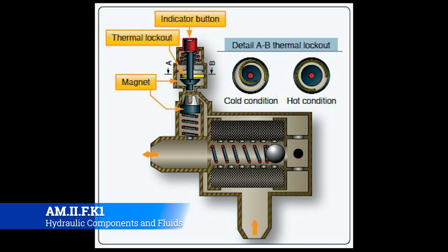So whenever you're doing post flights or you're doing dailies or something like that, it's really a good habit to get in, and it's a good professional way to go about it. Always put your hand on there, and bonus points if you take a shop towel and wipe everything off. Just cleanliness generally leads to being able to maintain the aircraft to a high degree of professionalism. And then on top of that, if there's any kind of hydraulic fluid leaking out of that system anywhere, you're going to pick it up on that shop towel really fast, and then know that there's something you either need to watch or need to address right then and there.